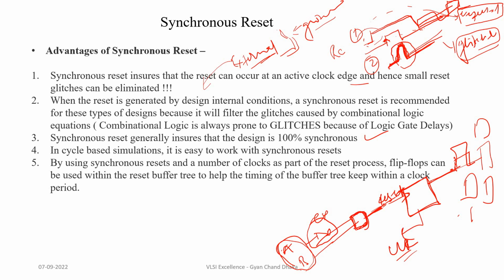The next advantage is using synchronous resets and a number of clocks as a part of the reset process. This advantage comes with the reset tree. If we have a reset tree designed, and if the reset tree delay is too much, then we can insert flip-flops, because the reset is already synchronous.